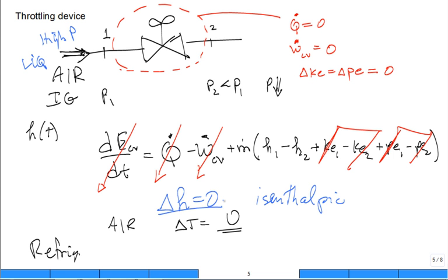Put a liquid refrigerant, high pressure, in. What's going to happen across it? Guess what the temperature does? Goes down. That's impossible, Professor. How can you have a fluid going through this simple little device and it comes out cold? There has to be heat transfer to make things go cold. True or false? In your mind, that's what you're saying.